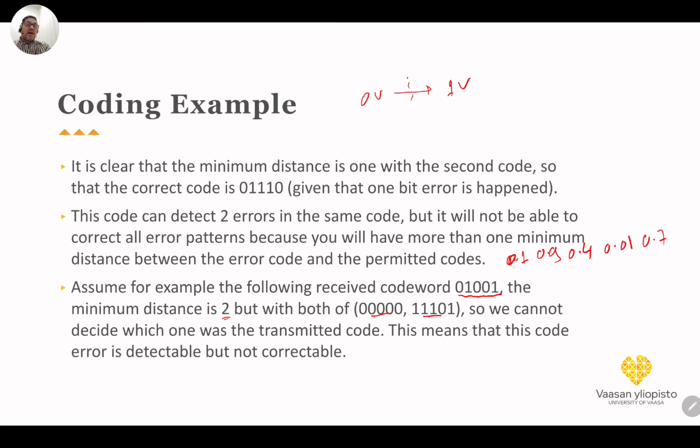After the hard decoder, of course, they will make this 0 and this 1 and this 0 and so on. However, the probability that 0.01 is 0 is higher than the probability that 0.4 is 0. However, in the threshold or hard decoder, they will treat them in the same manner. Both will be 0, because each is less than 0.5.